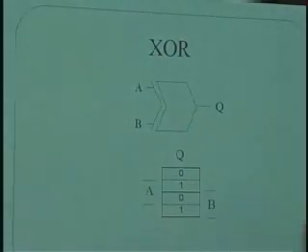Okay? This is the light switch circuit. This is exactly the light switch circuit. If you have 2 switches for 1 light, right, or even 3 if you set it up with 3, and the one at the top of the stairs works one way, and the one at the bottom of the stairs works the other way, they work as an XOR. So either switch can always change the state of the light, which is exactly what you want to have work. How many people actually know how to hook that circuit up? Anybody here know?